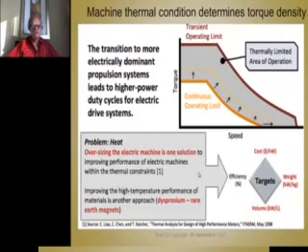But the other thing to do is to improve the thermal capacity and the thermal rejection of the machine by using the right materials and allowing the machine to run hotter. You can do that. For example, if you're limited by magnet temperature, you can use higher performance magnets, like rare earth magnets doped with dysprosium to increase the temperature capabilities. There's one company, Electron Energy Corporation in Pennsylvania, under a contract with the Air Force, that has developed rare earth magnets that operate successfully at operating temperatures of 550 degrees C. But all these things you have to consider: heat versus cost versus weight versus performance versus volume.